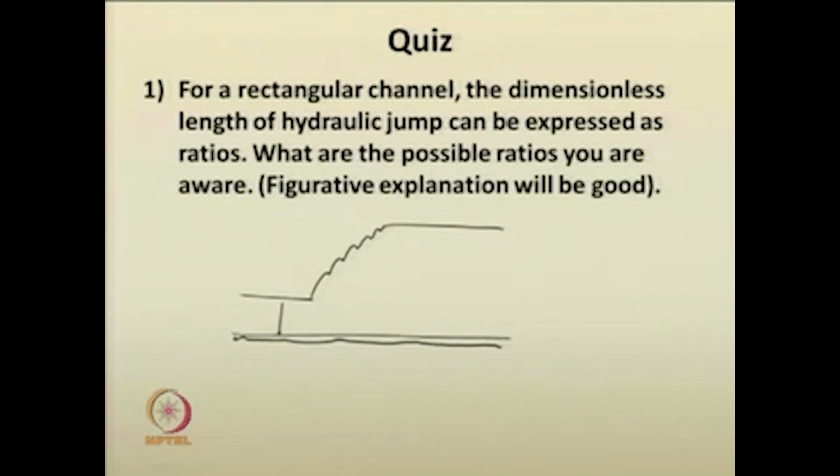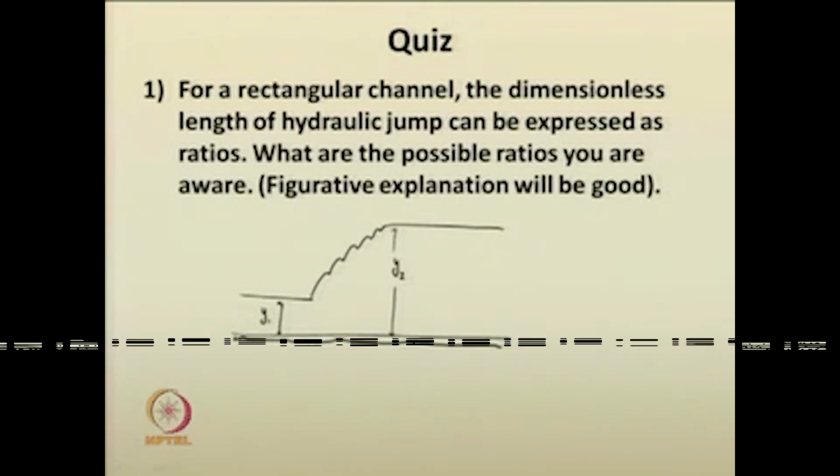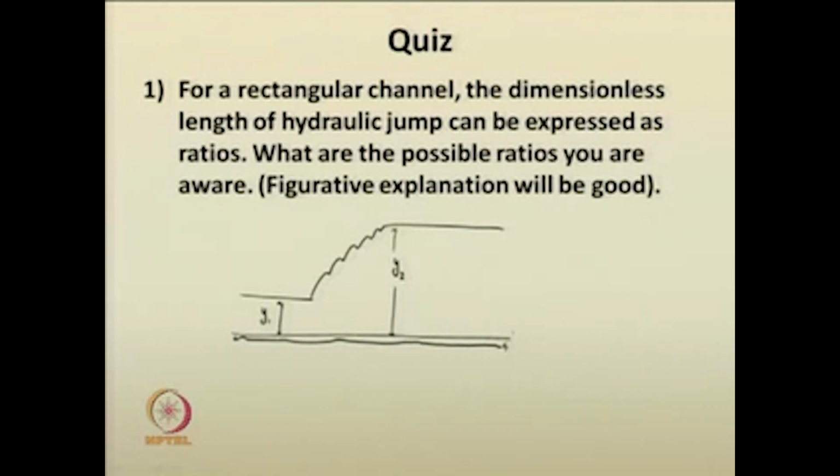It has a pre-jump depth and a post-jump depth. The starting of the jump to the portion where the rollers in the jump conclude, which is haphazard, that is called the length of the hydraulic jump.